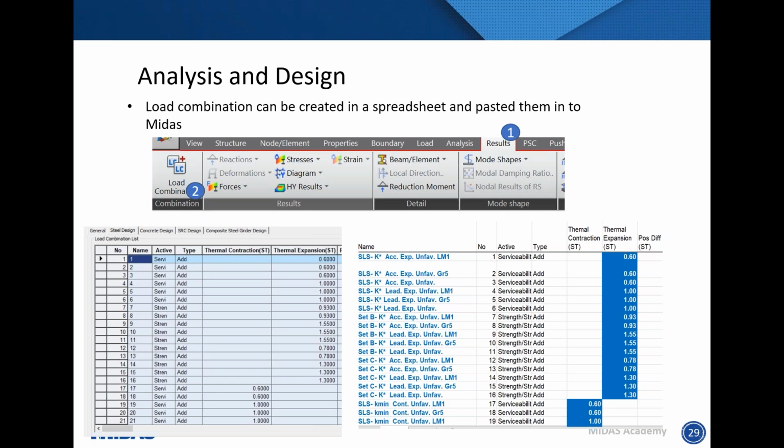The reasoning for doing this is it allows you to figure out how many cell column positions you have for each individual load case, which is quite a key factor for your analysis. Further to this, as you go through this part of creating your load combinations, you also have the option to distinguish loads between serviceability or ULS analysis. This is quite important if you are using the design modules within the software.